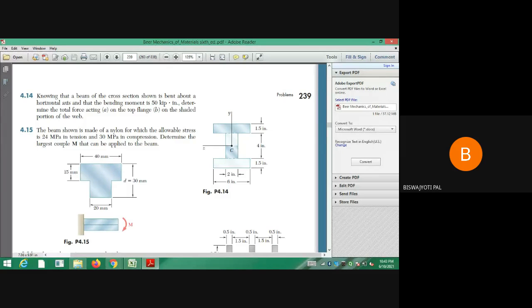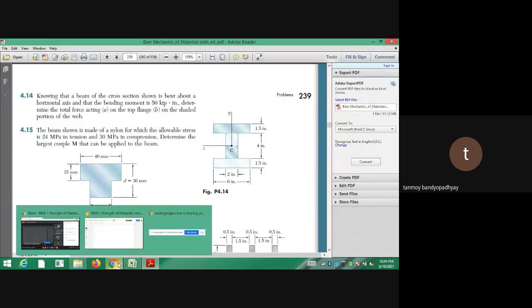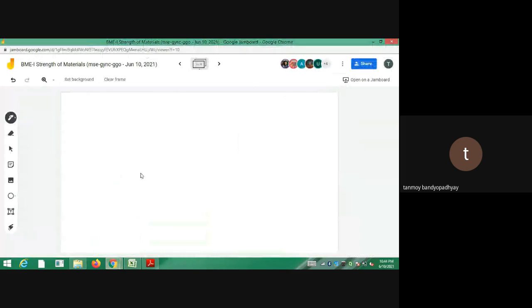Correct. So what are the values given? They have just given top and bottom, and they have given tension and compression. You determine which one is which. So now in this problem, from the figure, as we can understand, since it is a hogging moment, the top one will be in tension, right? So the top fibers, I have drawn it also. You see that the top fibers will be in tension and the bottom fibers will be in compression.